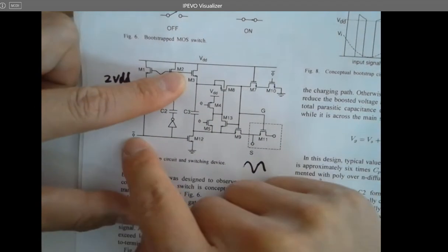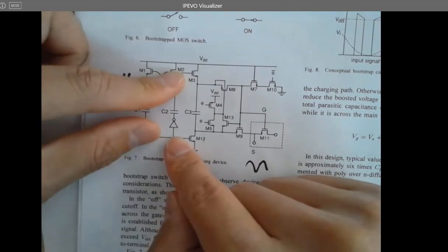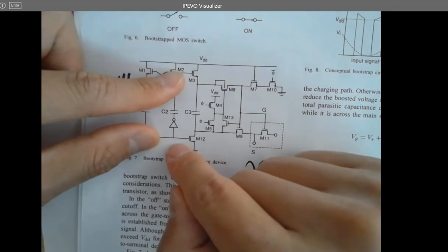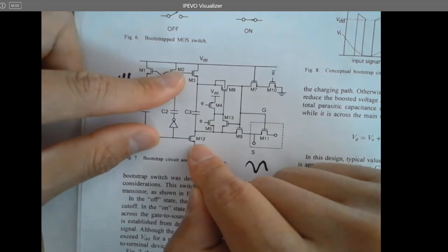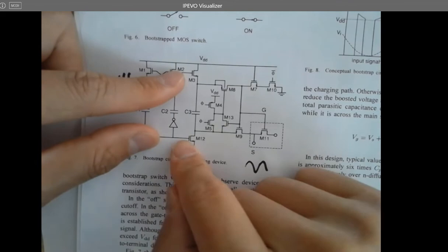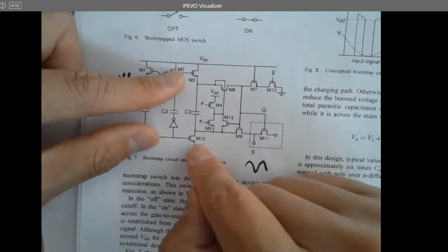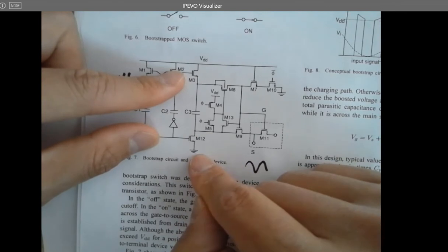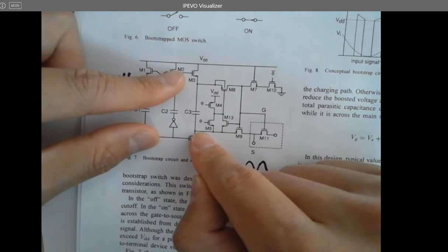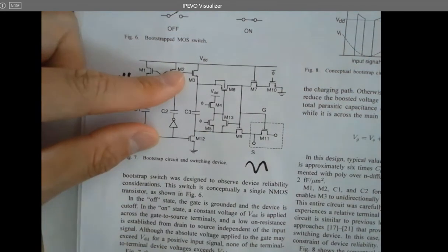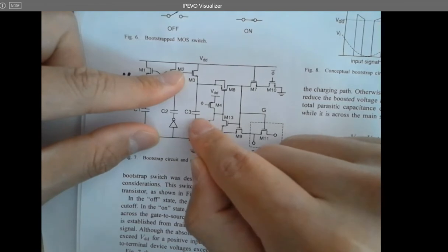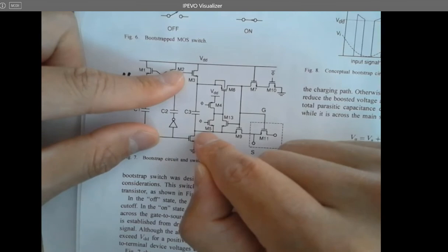So imagine that whenever this phi bar, whenever this clock signal, don't think about the bar, doesn't matter, just look at this line. Whenever this data line is high, what's happening? Whenever this is high, the gate for this M12 is high, what's happening? Don't think about others, just look at M12. If I turn on this gate, what's happening for the drain of the M12? So I open the channel, it's pulling this node down to the ground, right? So it's going to give you a falling edge to this node. It's pulling the bottom plate of the capacitor to ground as well at the same time. Is that making sense for now? So I turn on this transistor, it's going to pull this to the ground.